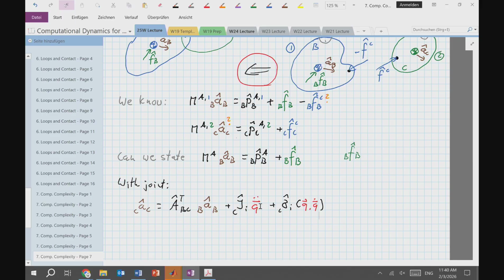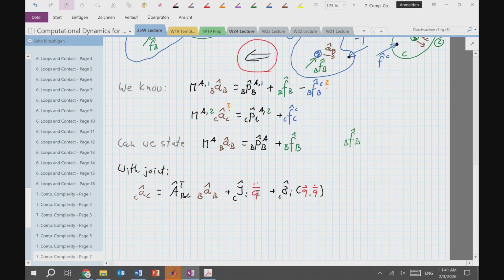I know that this rotational joint, with a single rotation axis, is going to block rotations about the other two rotation axes. So there's a lot of information in here which reduces these 6 unknowns to just one. If I have a ball and socket joint, this would be a 3-dimensional quantity. Depending on what type of joint you have, we will reduce this to fewer dimensions.